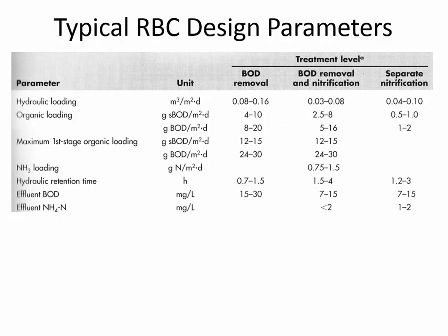And so if you have, let's say, a flow rate like we had in Huntington, the kinetics of an RBC are about the same as activated sludge, maybe not as high, because in activated sludge you've got so much more surface area because the particles are really small and moving around. And so it could be like a 1-day contact time in the RBC, whereas in the aeration basin, the hydraulic detention time maybe was half a day in activated sludge.